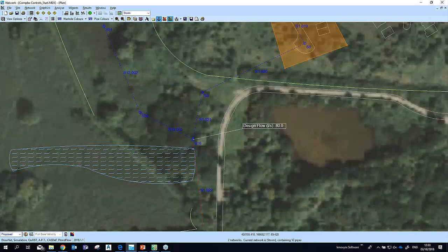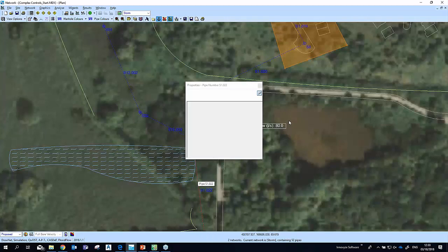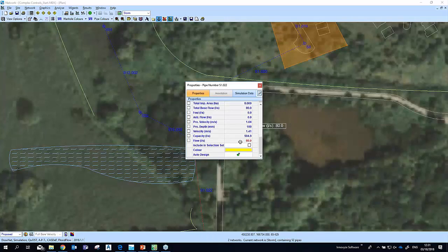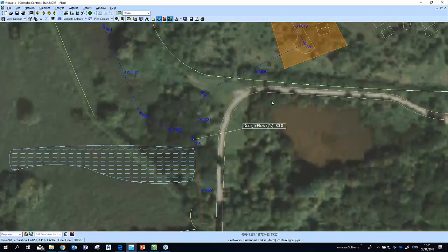So you'll see I've just, in the properties of my pipes, added in a design flow in here, and therefore my pipe will be sized appropriately. This allows me to downsize pipes behind flow control chambers and can really speed up the process. So someone was able to complete the design of the pipes and attenuation network. I'm going to come in now and do the slightly more complicated design of the complex flow control into this manhole S10, my flow control chamber.